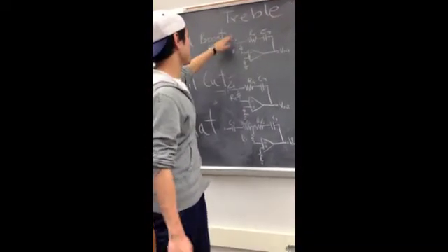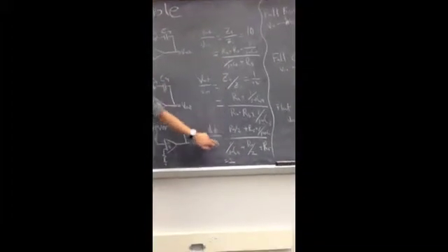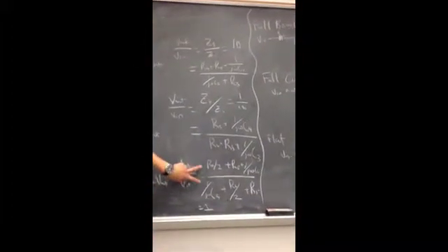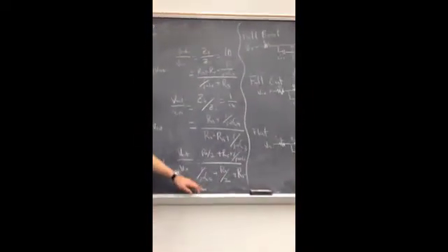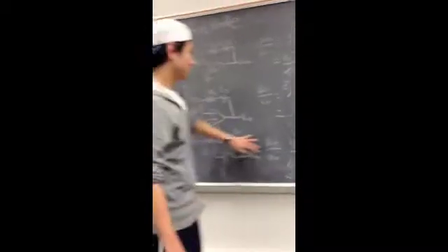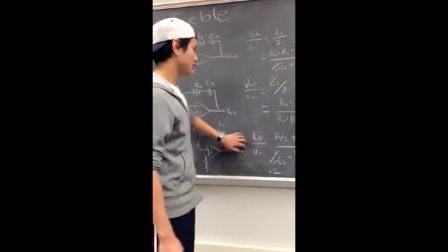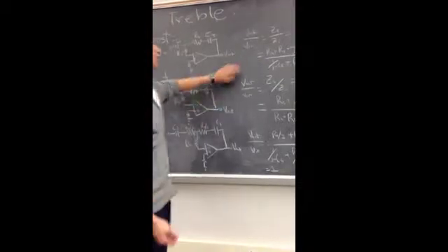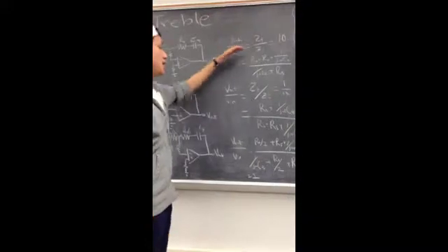So basically, we diagrammed the select components that contributed to these respective impedances. As you can see from these values, we should have picked the same capacitances, so that regardless of frequency at flat, V out over V in was going to equal 1, and there was going to be no effect from the tonal control.